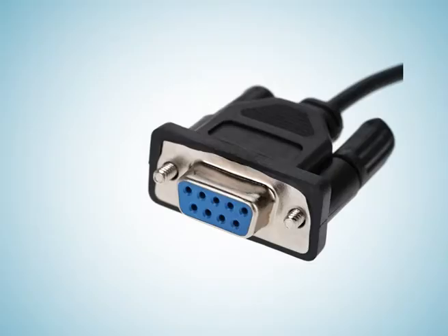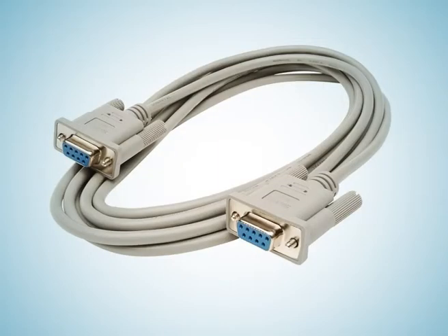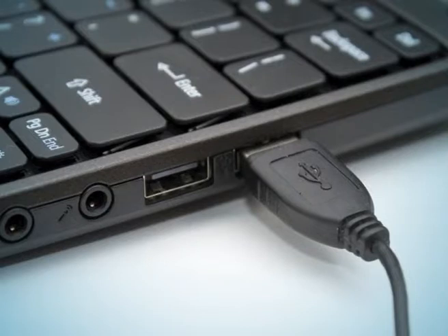An RS-232 serial port was once a standard feature of a personal computer. It was popularly used for connections to modems, printers, mice, data storage in cassette tapes, uninterruptible power supplies, and other peripheral devices. However, RS-232 is hampered by low transmission speed, large voltage swing, and large standard connectors unsuitable for laptops and tablets. In modern personal computers, USB has replaced RS-232 from most of its peripheral interface roles.